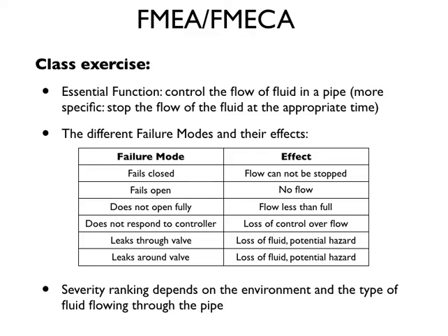Does not respond to the controller, there's a loss of control over the flow, and that actually plays into some of the other ones, because the loss in control may result in a situation where there is a failed open or a failed closed, which then leads to the effects on the top right. So there's a little bit of propagation of failure depending on how you look at this.